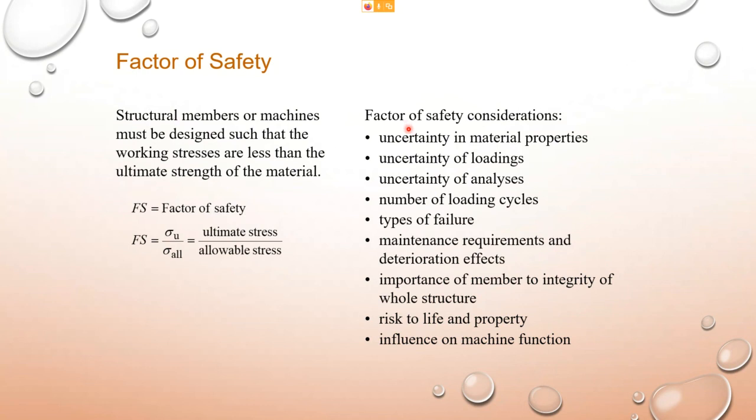I can tell you, if you use a smaller value of factor of safety, the material that you can use is wider in range. Wider in range means you can choose a lot of different materials, maybe cheaper materials for your design. But with a higher factor of safety, the limitations of material selection become greater because the materials become more expensive as the factor of safety is greater.